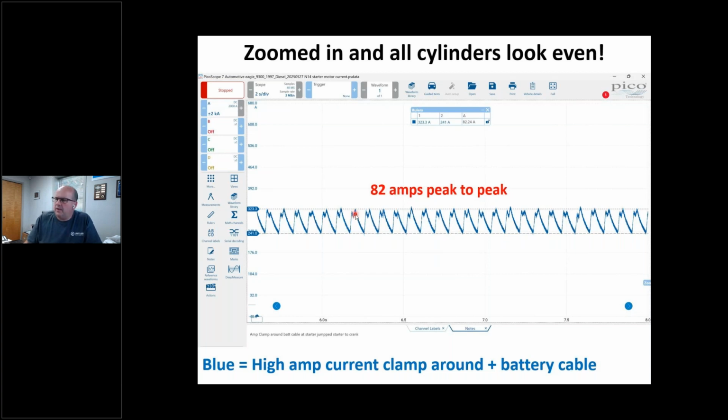Would you agree that all these peaks are pretty much all the same? If this N14 Select came in here and it had a misfire and it's shaking or whatever, don't I need special tools to check compression on this? Don't I have to have some kind of apparatus? Don't I have to pull a valve cover off? This thing's got a Jake brake in it. You have to take the Jakes out of there. This is a lot of messing around to do a compression test. Would you agree? Even though I didn't put a gauge in it, I know one thing.